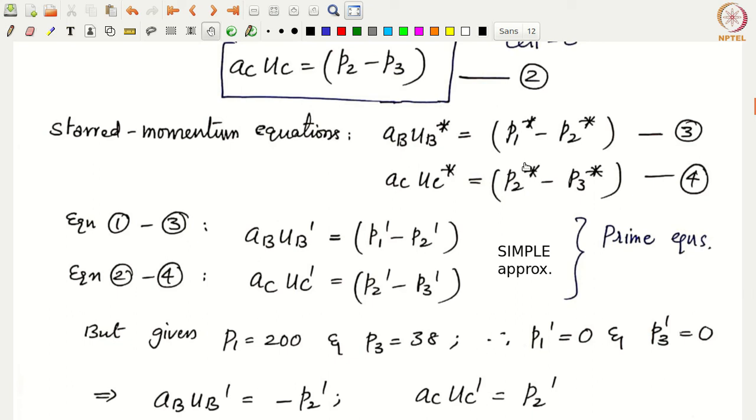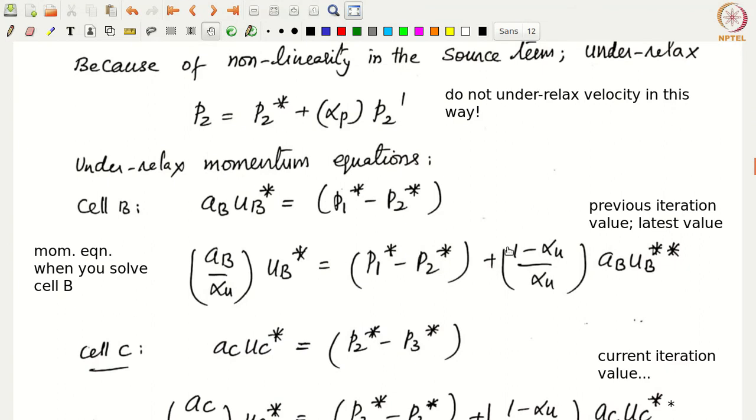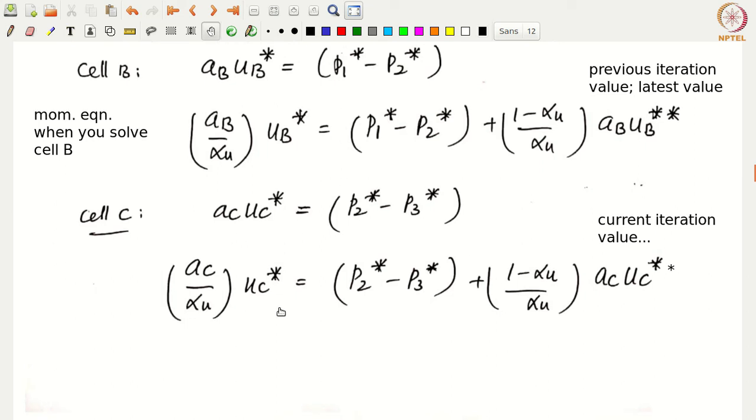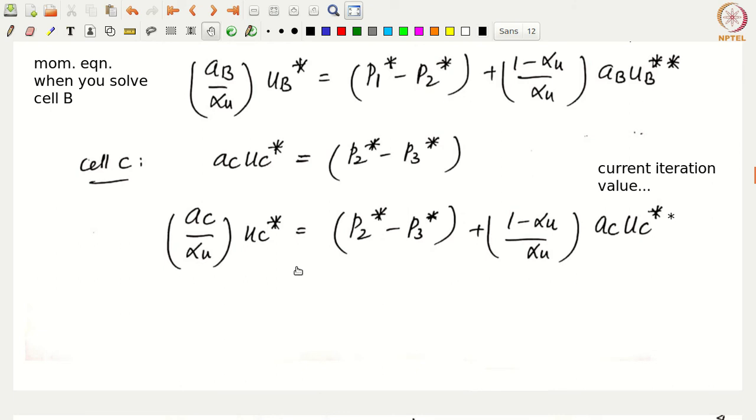Now the idea is, even if you use the under-relaxed equations here, in the SIMPLE approximation those terms also will be neglected, just like the sigma A and B U and B prime. The contribution coming from this sigma A, B, U, B primes also will be neglected, so essentially they will not be considered. That is the simple approximation. As a result, it doesn't matter whether you had used the under-relaxed equation for deriving the velocity correction, pressure correction equation, or the regular equation. Okay, fine. So that finishes the setting up of the first problem, that is problem 6.4.